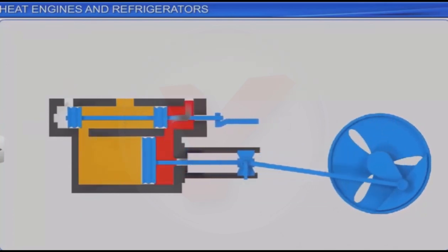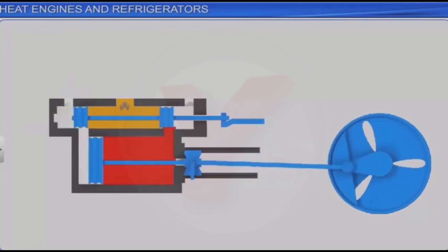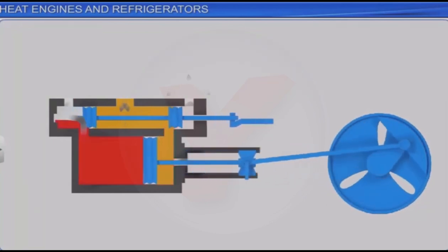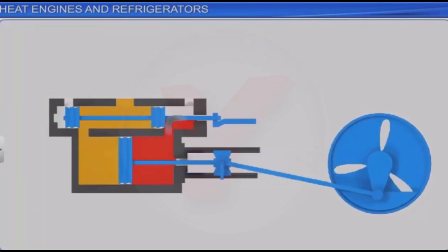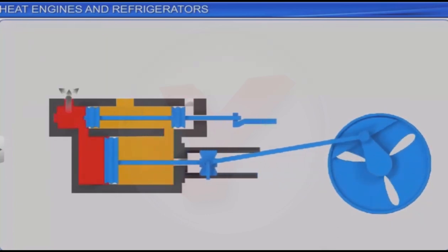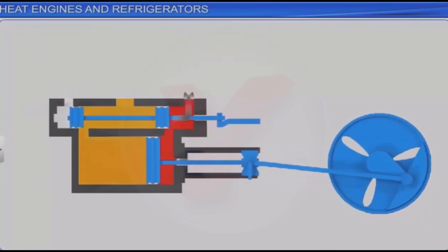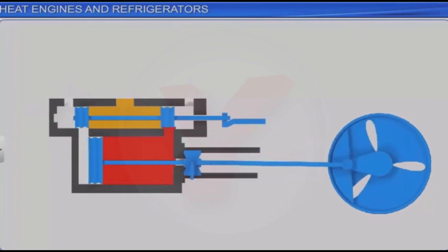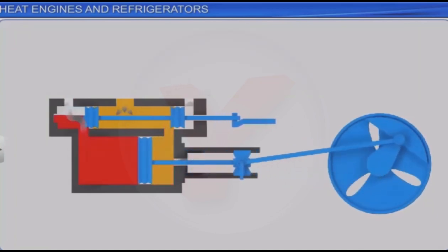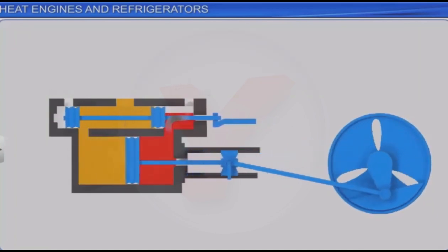Note that the movement of the sliding valve is controlled by a separate gear system. The movement of the valve is used to control the steam that enters the main cylinder and the speed with which the piston oscillates.